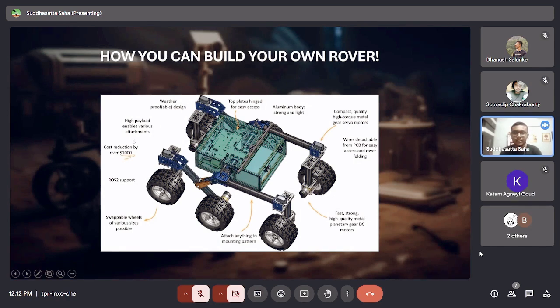Or even stay stable for that matter. So your pictures will be extremely hazy and things will not be stable at all. So if you deploy this type of a wheeled mechanism, no matter how harsh weather condition comes, in most of the scenarios it will stick to the ground inertia and try to maintain traction, and it will perform better experiments and have more stability overall. So I hope that answers your question, right?